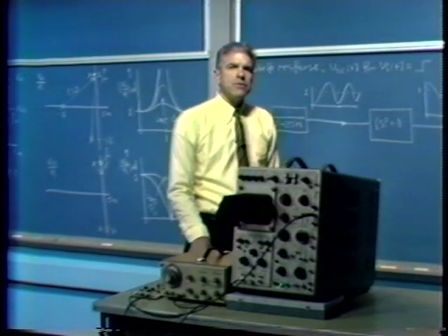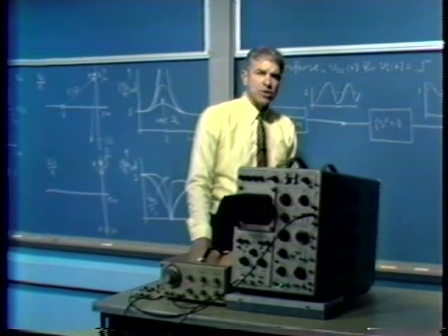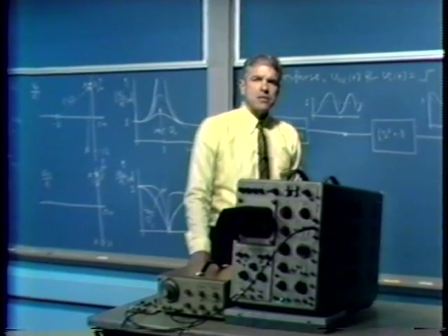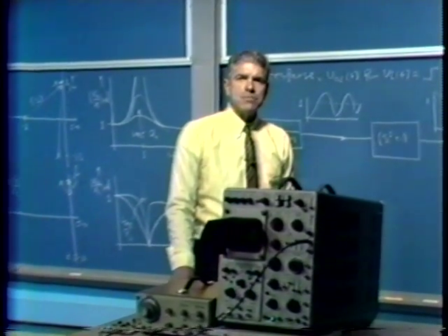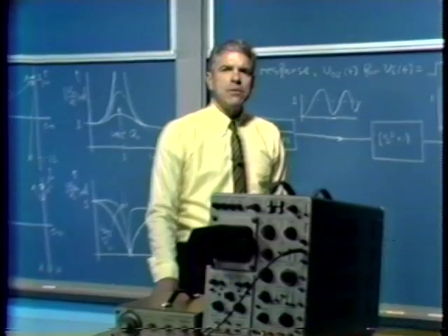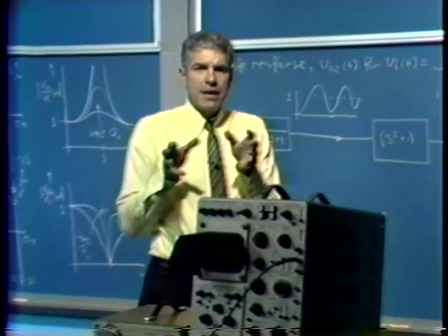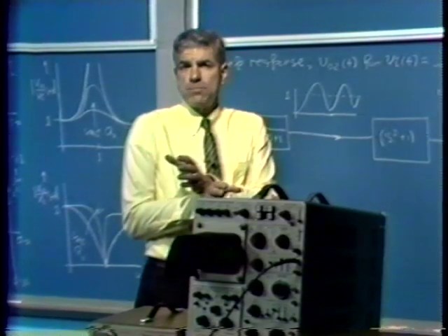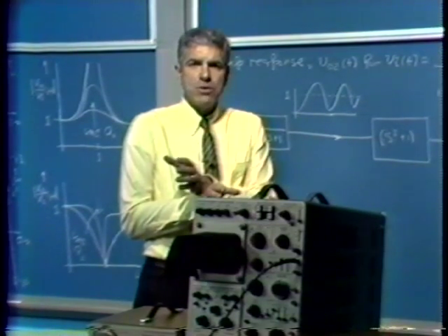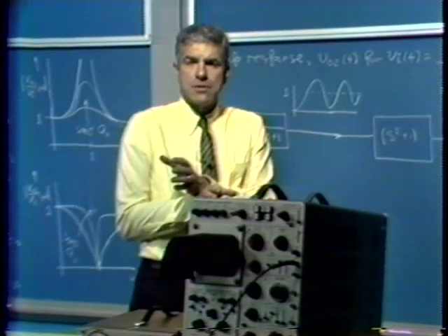It turns out what we can do to estimate the response of the rejection amplifier is exploit a property of linear systems. If we have a linear system, we're able to, conceptually at least, shuffle the blocks in a block diagram in any order that's particularly convenient for us. And what I hope to do is choose one that's fairly easy for analysis.